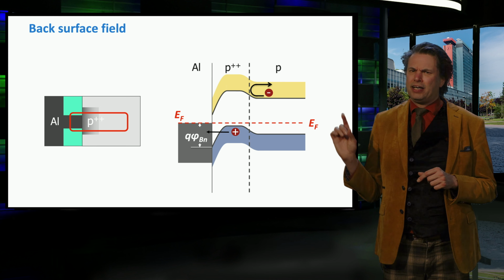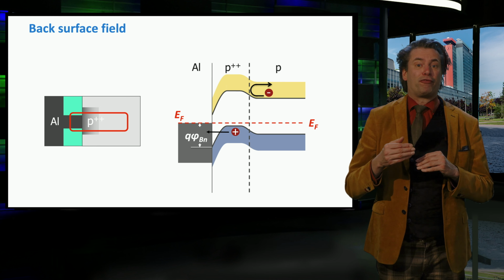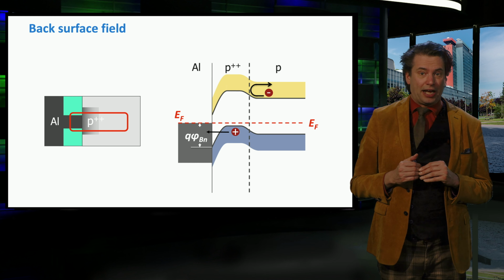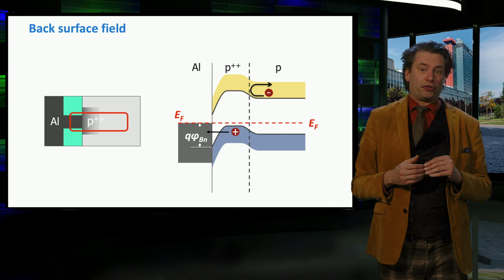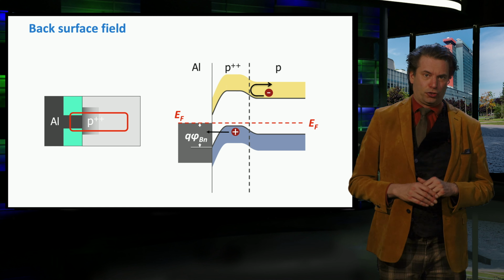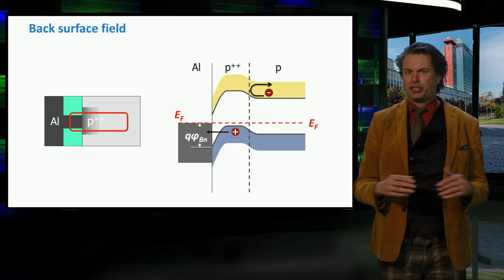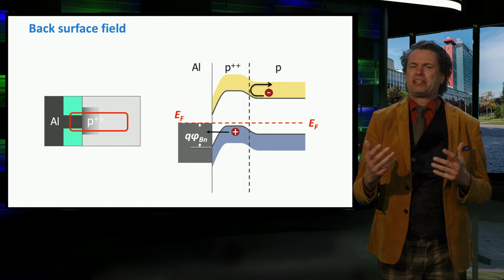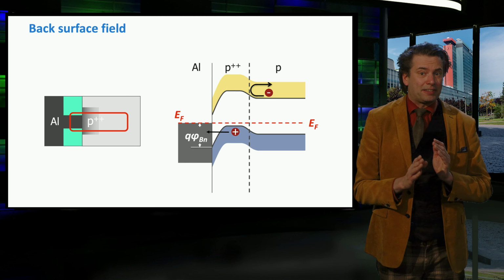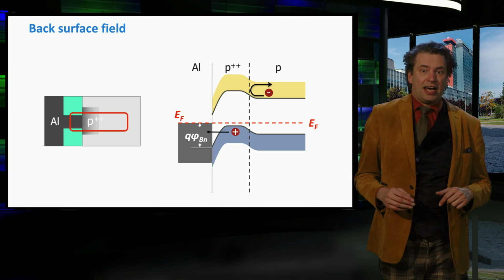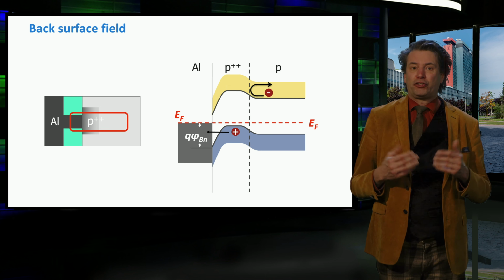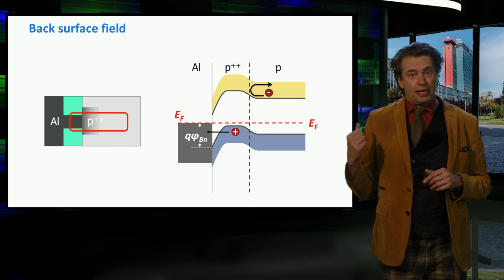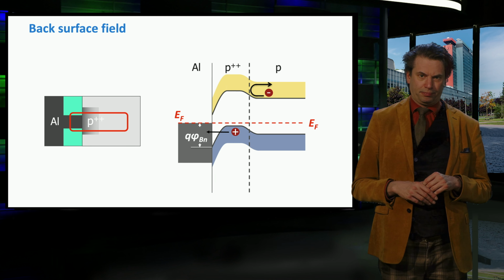In this case, it will act as a barrier for the light-excited minority electrons in the lower doped region to diffuse to the back surface. The space charge field behaves like a passivation of the defects at the back contact interface and allows to have higher levels for the electron minority density in the p-doped bulk.